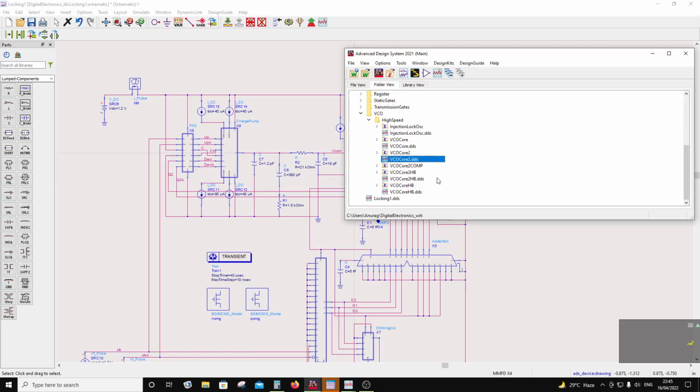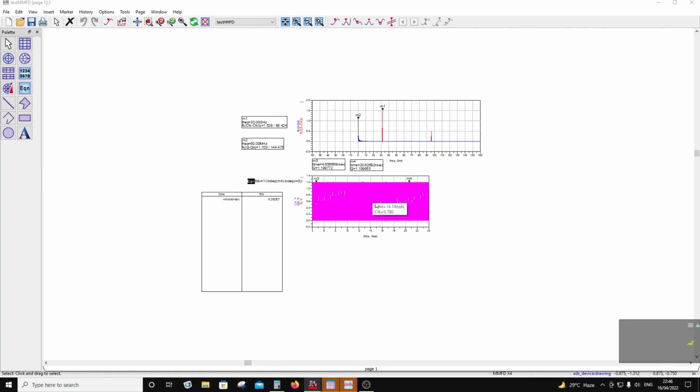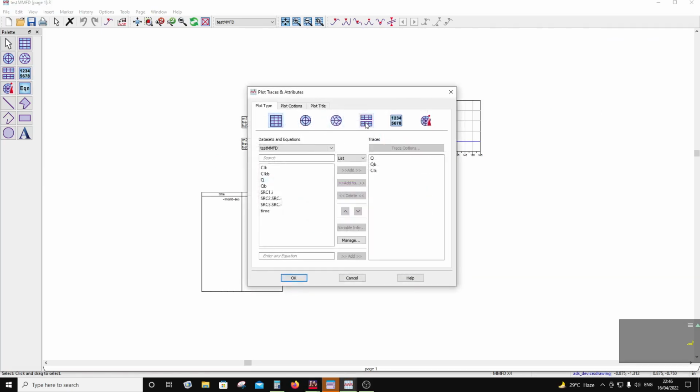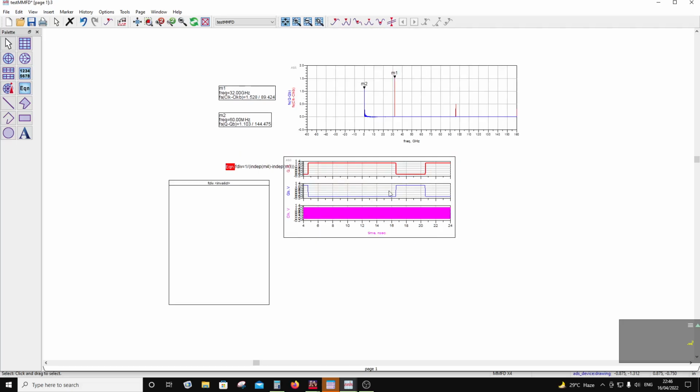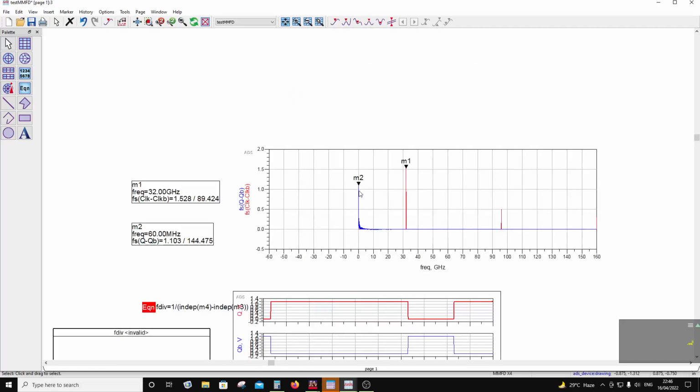If I was to go here and look at the test of this, so if I go to PLL blocks, let's look at the multimodulus divider. Okay, so I am dividing, let me just split this up. Basically this is one cycle of division, and how many cycles will it have? It will have basically 372, right? So that's the entire divide ratio, right?